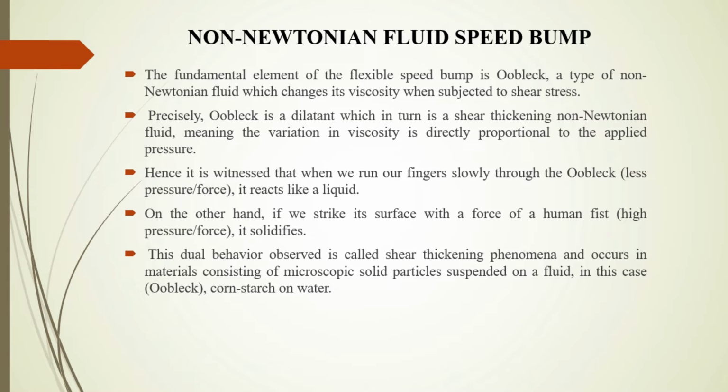And next, non-Newtonian fluid speed bumps. The flexible speed bump is oobleck. It is a type of non-Newtonian fluid which changes viscosity when subjected to shear stress. Oobleck is a shear thickening non-Newtonian fluid, which means the variation in viscosity is directly proportional to the applied pressure.